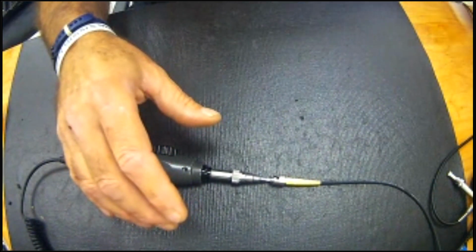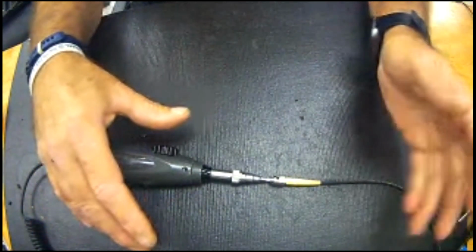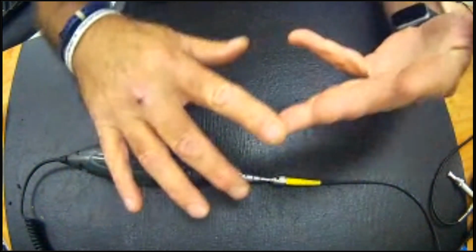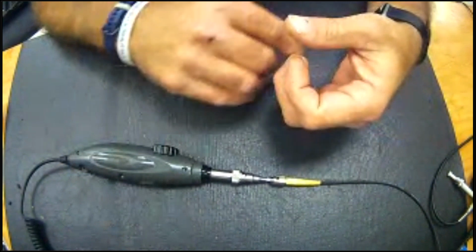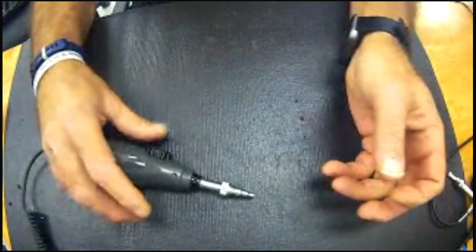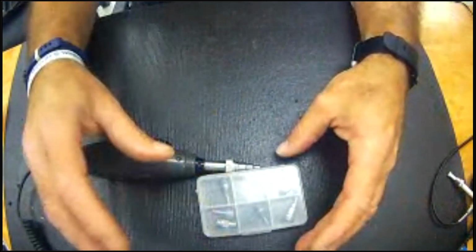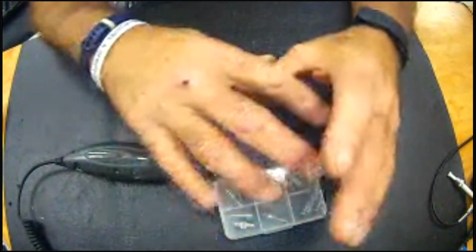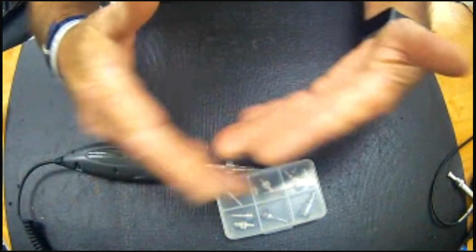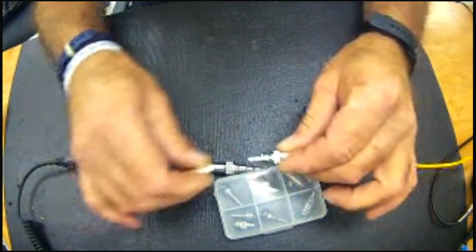I believe your best approach to any type of maintenance is to clean it before you use it and clean it after you've used it and put it away. I wish everybody did that. So owning a video scope is imperative, in my opinion. It comes with lots of different tips to be able to plug into many different types of connectors, whether they're receptacle-based or exposed ferrule designs.